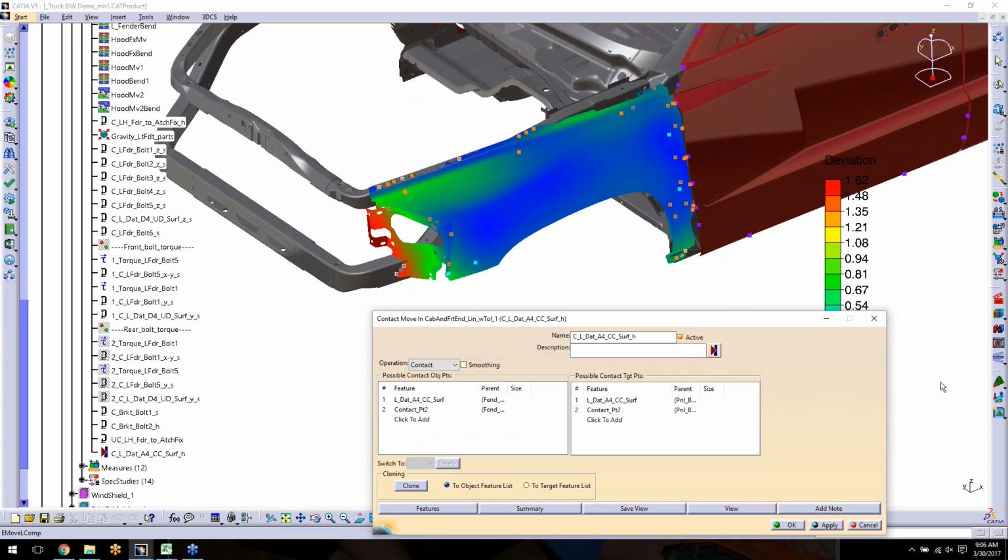And then how is torque different than a hard clamp, especially if using a soft clamp after torque? That has more to do with the direction of the force. So a torque move, you saw there's a choice between force and torque, because force is a single directional force effect, while torque is a rotational force. So on this particular part, when you're using torque, it's going to twist the part as you're screwing in that bolt. Is that correct, Maria?